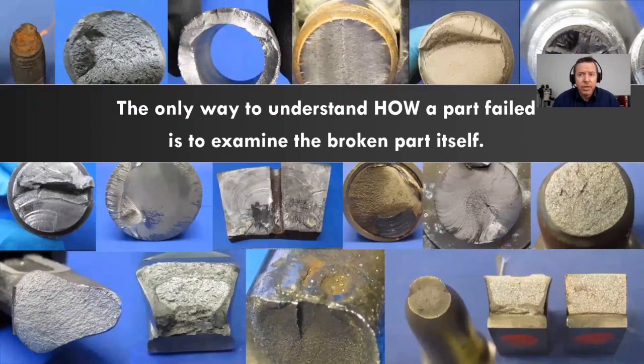To diagnose how a part failed can only be done by examining the failed part. I appreciate that reliability engineers, rotating equipment engineers, or a lot of mechanical engineers will do the very best they can to get as much data as they can from around the failed part: vibration, histories, and that kind of stuff. But until you actually examine the broken part itself, you're always going to be a little bit of guesswork.